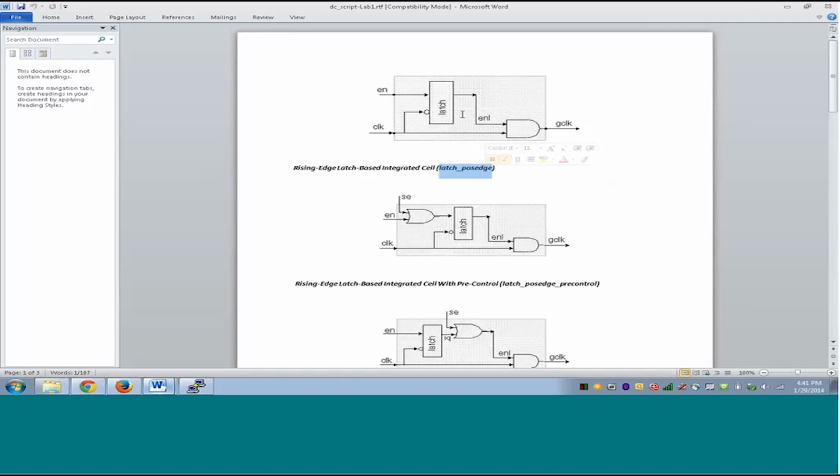What it means is that there will be a latch, of course. Clock gating without the latch is not a good method because it creates a lot of problems. The timing becomes much more complex. The latch makes sure that the enable at this point does not transition.